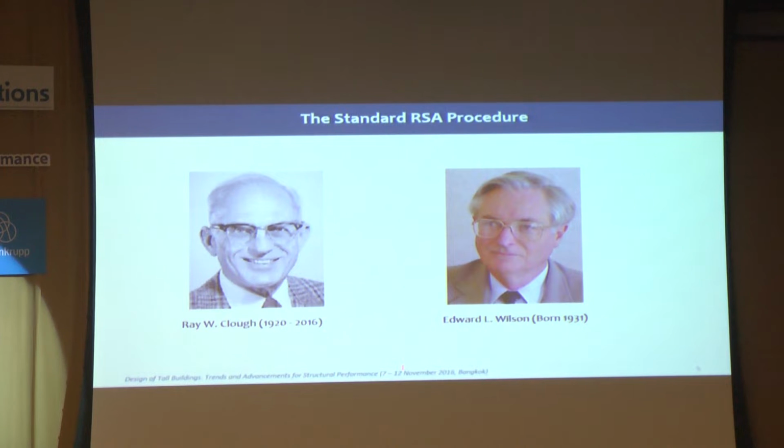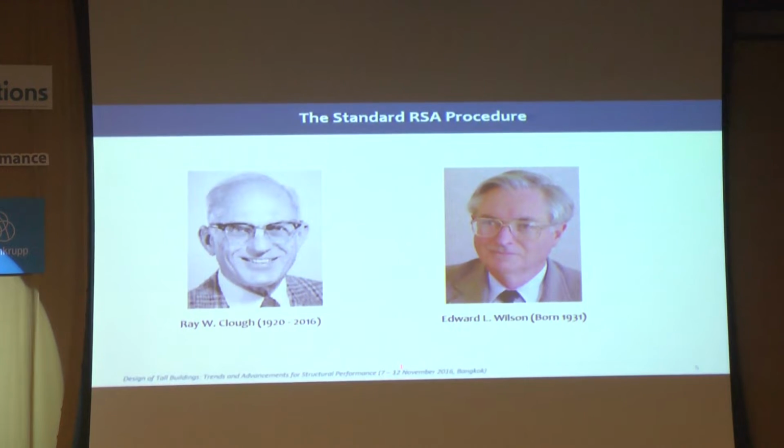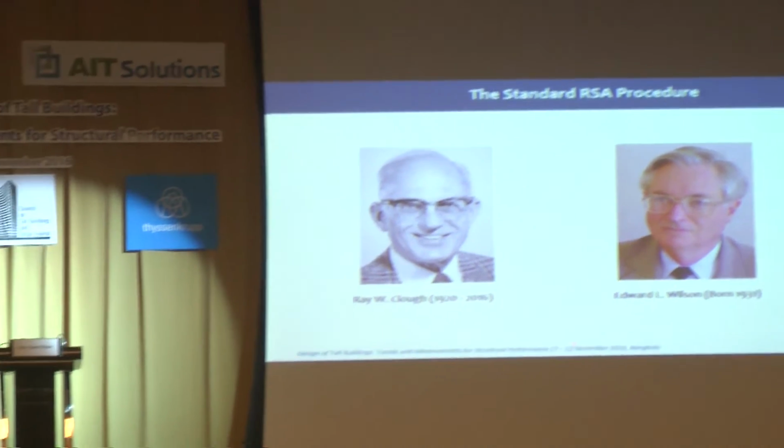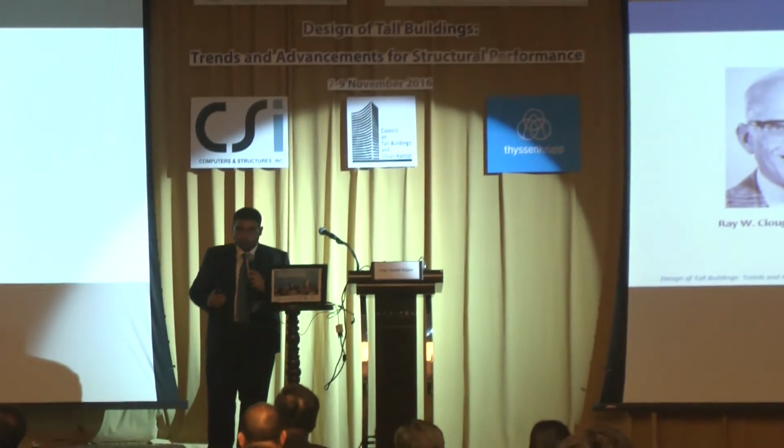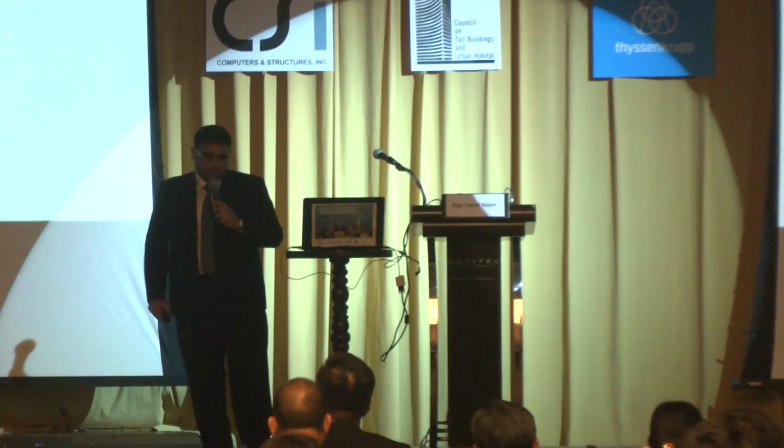I am not in a position to say something about the future of response spectrum analysis, but we feel that the idea of modal superposition is so simple and elegant that if you take it out of structural dynamics, all you are left with is time history analysis, which is kind of a black box. You don't know what the engine is doing itself.